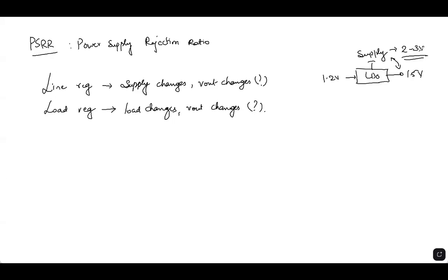That's a different thing. But there is a possibility that you have already built an LDO, but somebody who is verifying it gives a supply beyond what you have designed for. You might have designed for 2 to 2.5, thinking that our supply will vary only between 2 to 2.5. But the verification guy is given an additional target to verify even at 3 volt.